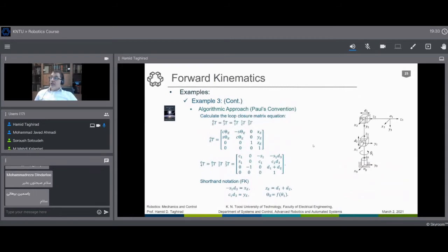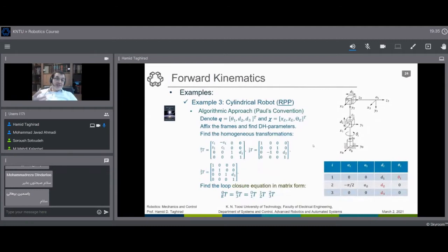And usually a general manipulator has 6 degrees of freedom, 3 degrees of freedom for position, as we talked before, and 3 degrees of freedom for orientation. Usually we have a base. This base could be cylindrical, it could be 3R, or it could be many different approaches, usually with three parameters as we have here. And we have a wrist.